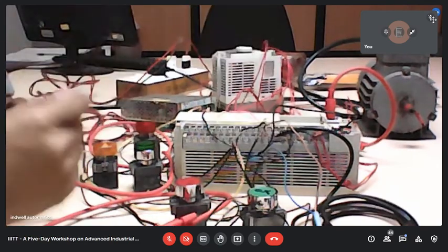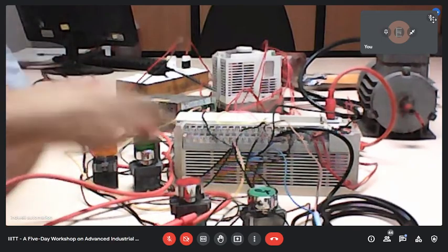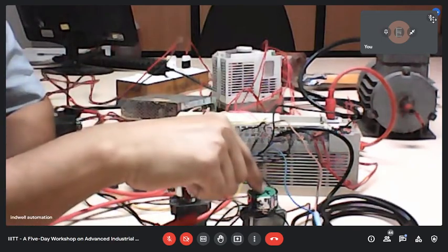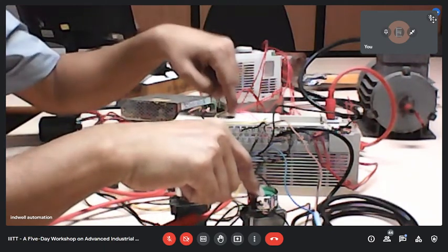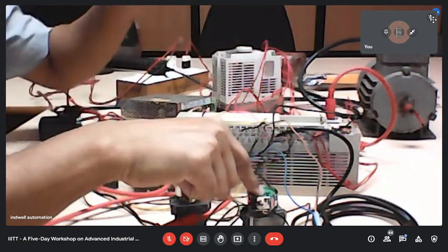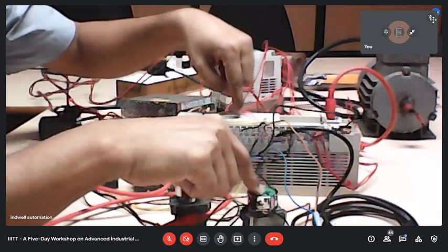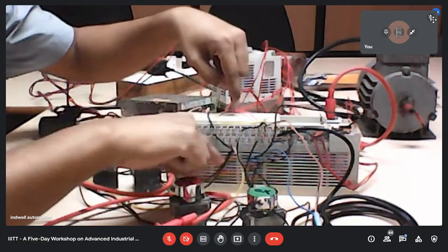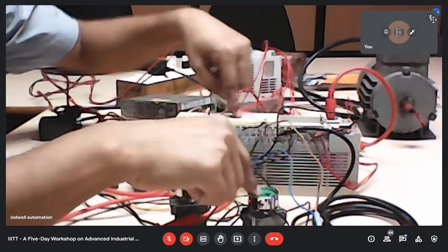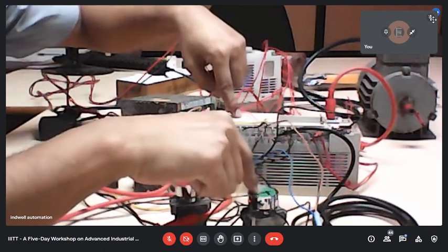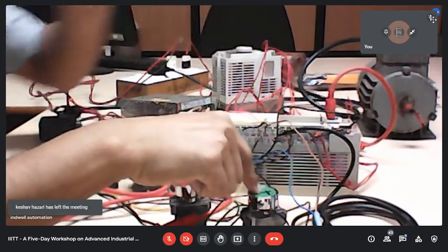So very first what you should do, I'm telling you the practical things, how we check. First you should press this and should check on your PLC indicator. I had shown you the input indicator. You should check whether your indicator is on or not. Yes, I can see my X0 indicator on PLC is on. It means there is no problem of connection. Push button is working well.